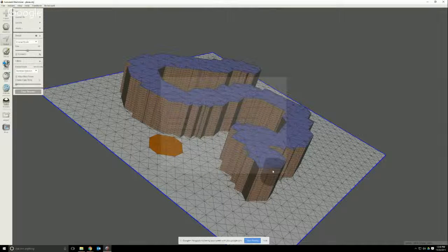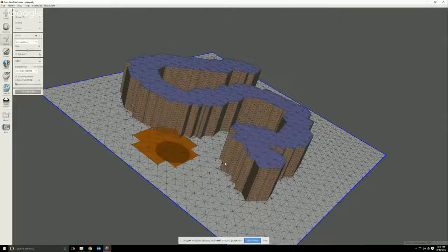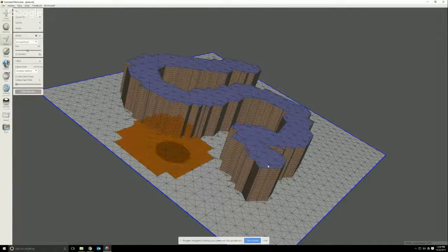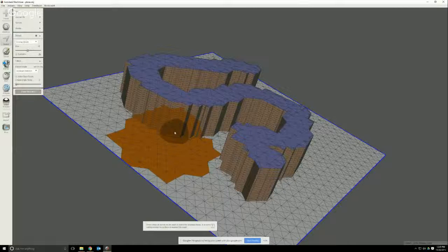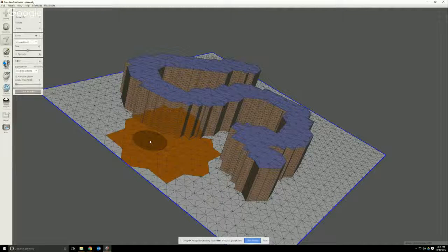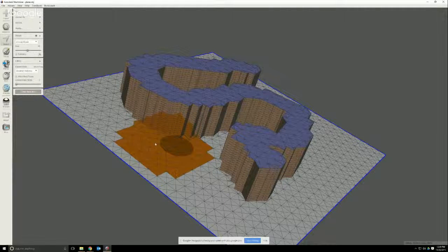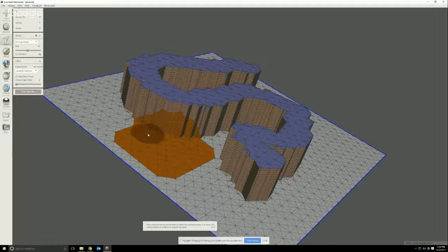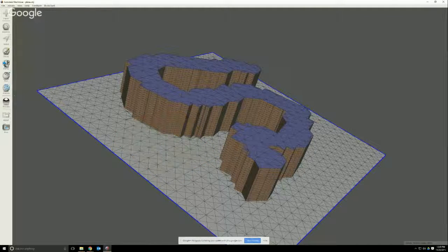So in this case, you have to do control right-click drag, and it actually starts expanding out ring by ring, which is kind of nice. It's a new way of selecting. As I'm expanding out, this is roughly equal to this, which we didn't have before. We just had go out by one triangle. So when it went out by one here, it would go out by one here. That's a really small area, and that's a really large area. But now with this geodesic distance, you can get roughly equivalent areas. Very cool. But anyway, that's not what I'm talking about.